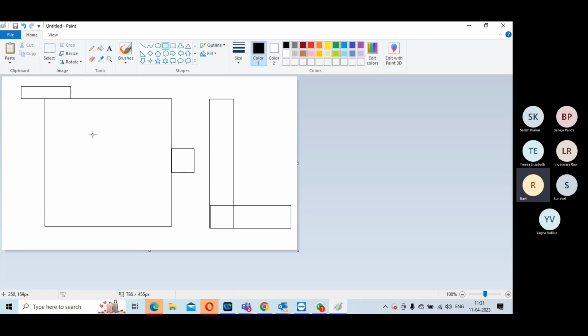See, first of all, you cannot place any macro that will fit this size. Irrespective of macro, you have to have a data flow diagram. That's the most crucial thing. You have to look at your hierarchical browser, irrespective of your tool. I'll give you that floor plan also and tell you how to look at it. Let us say this is one module which is supposed to be placed here, let's call it module A, and module B is supposed to be placed there.